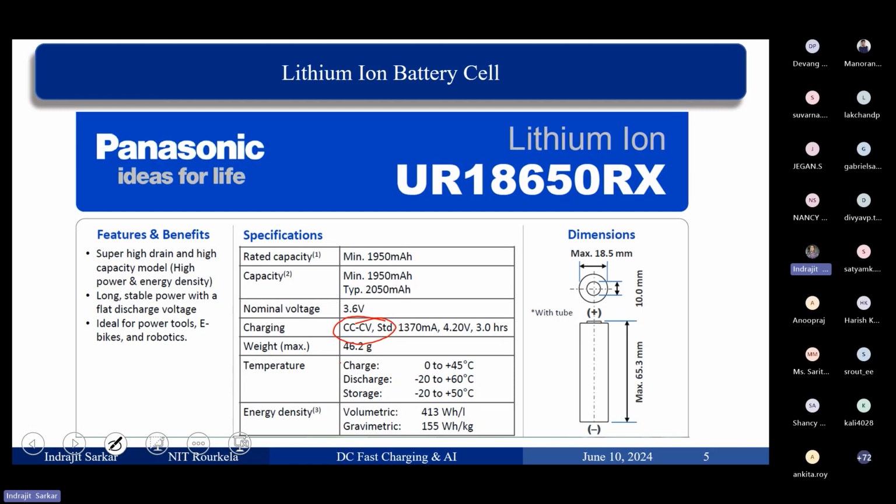If you keep it for the entire time, there will be a time after which the tank will overflow. In order to avoid that, you monitor the water level, and when 80% water level has been reached, you change the flow rate and subsequently reduce it so that overflow doesn't happen.